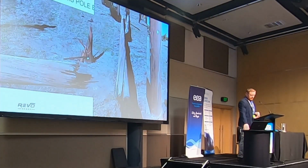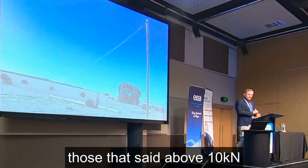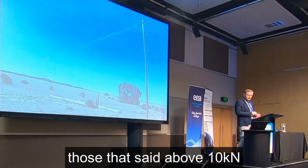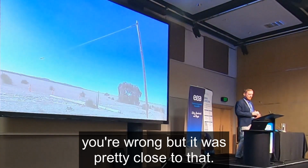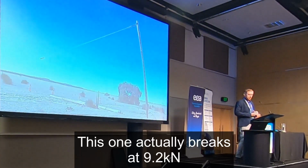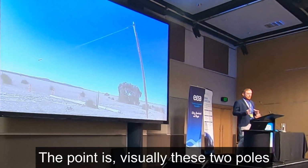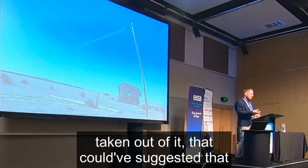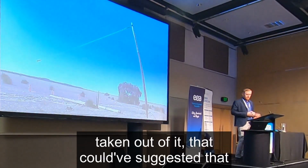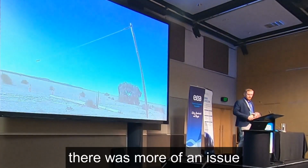So those that said above 10 kilonewtons would be wrong, but it was pretty close to that. This one actually breaks at 9.2 kilonewtons. The point is, visually, these two poles aren't that much different. In fact, this pole had a massive chunk of timber taken out of it that could have suggested that there wasn't more of an issue in there.